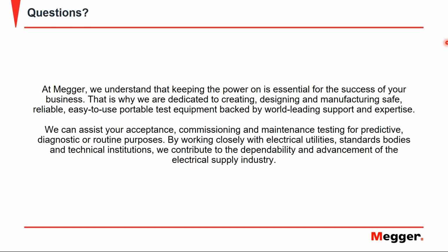Being able to do trending with your partial discharge measurements is also another valuable tool when we talk about evaluating a cable over its lifetime as you do repeated partial discharge measurements. So for those reasons, it's extremely important to go that extra step and put the effort into isolating both ends of the cable. And like I said earlier, I understand that in a lot of cases it is very difficult to do that. However, to be able to accommodate this testing, it's extremely important that you do that.